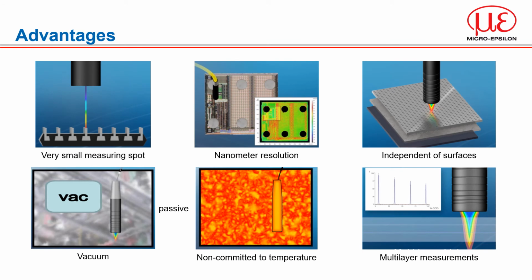Confocal chromatic measuring systems are increasingly used for fast distance and thickness measurements. Different sensor and controller models open versatile fields of application, for example in the semiconductor industry, the glass industry, medical engineering and plastics production. Unlike other optical measuring procedures such as laser triangulation sensors, confocal chromatic sensors are less known. However, confocal chromatic sensors stand out due to maximum measurement accuracy and high dynamics while measuring even shiny and reflecting surfaces where laser sensors are operating at their limits.